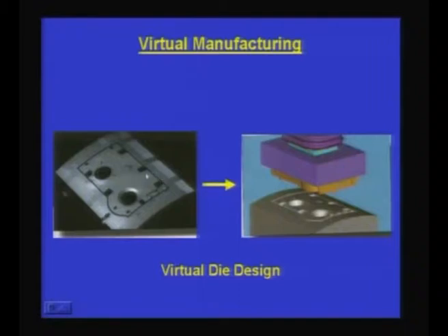This is actually a real part which one has to produce, for which you have already come up with a die shape. Now, I am carrying out a virtual forming operation, and I can look at the part which comes and compare it with the desired part, whether it meets the geometry and tolerances. If I have a problem, then I can correct the die shape, because of spring back or some other reasons I have a problem in achieving this.